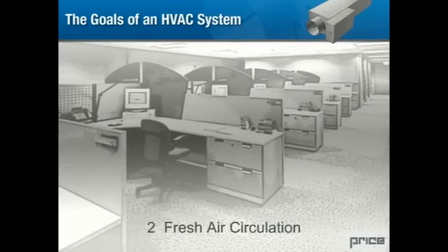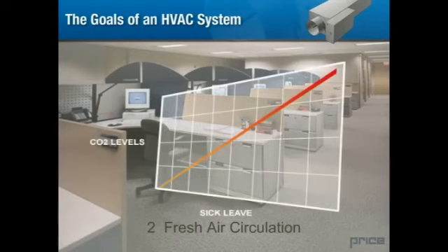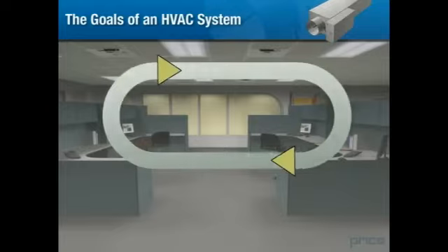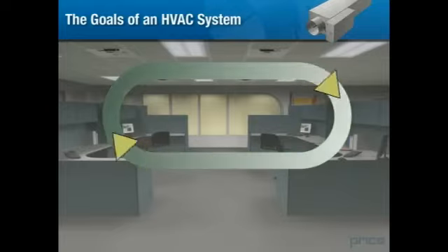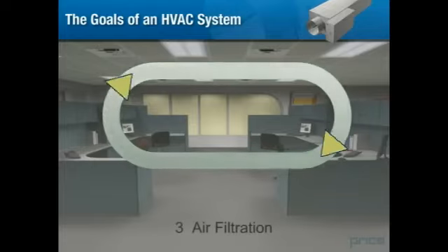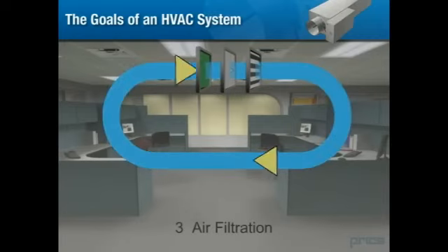If we introduce a significant proportion of fresh exterior air and alleviate carbon dioxide buildup, occupants experience better health and performance gains. Studies have shown a direct link between CO2 levels and short-term sick leave in office workforces. However, our concerns regarding the HVAC system and occupant health do not end here. In heavily air-conditioned, energy-efficient environments, recirculated conditioned air can carry contaminants which contribute to respiratory illness. It is the HVAC system's job to remove contaminants and dust from the air using filters at various stages.